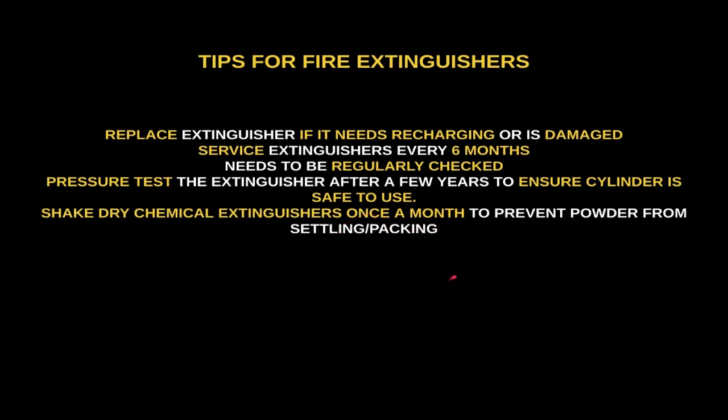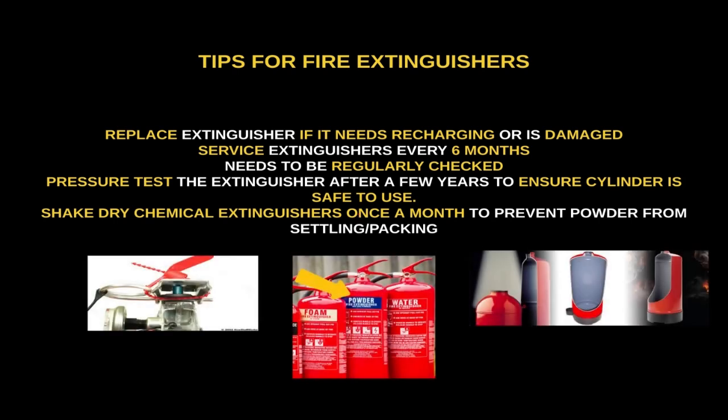So remember, we said we want to keep it at 45 degrees. This helps prevent powder from compacting. But to be safe, once a month, just shake the fire extinguisher to make sure that it is not settling at the bottom of the extinguisher.